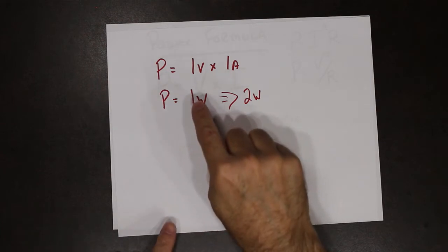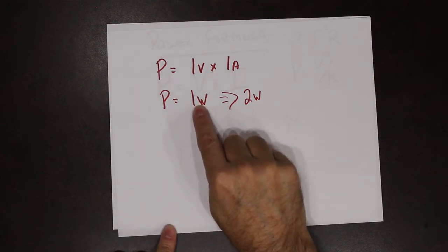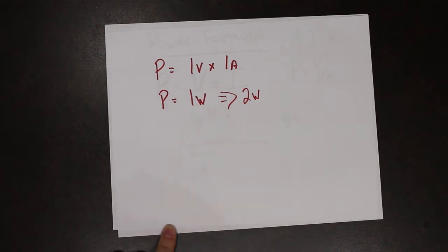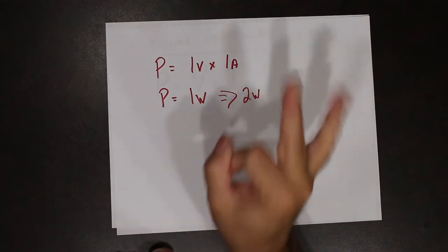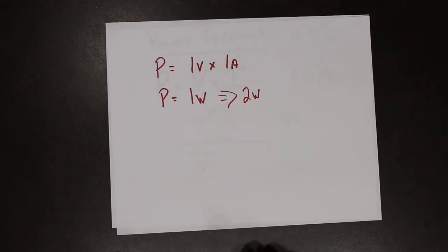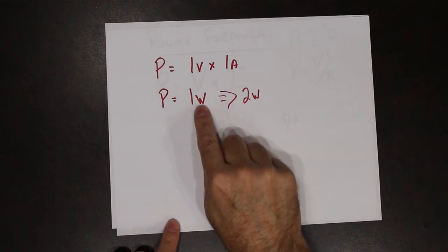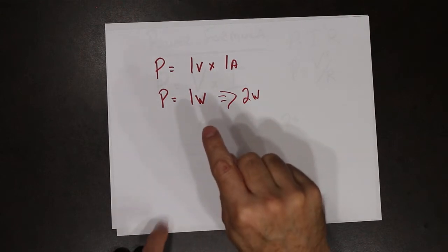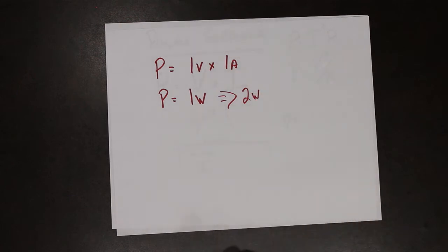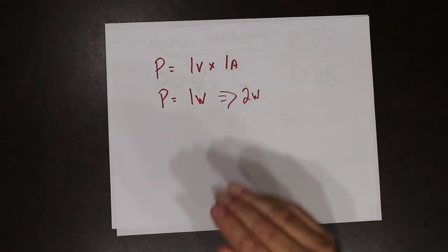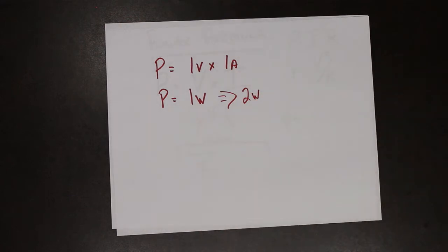So when we calculate the power, we get a value. When we're deciding on what physical size resistor to use, we take that value and typically we go to the next one. So we want to make sure we oversize the resistor just to build in some safety.